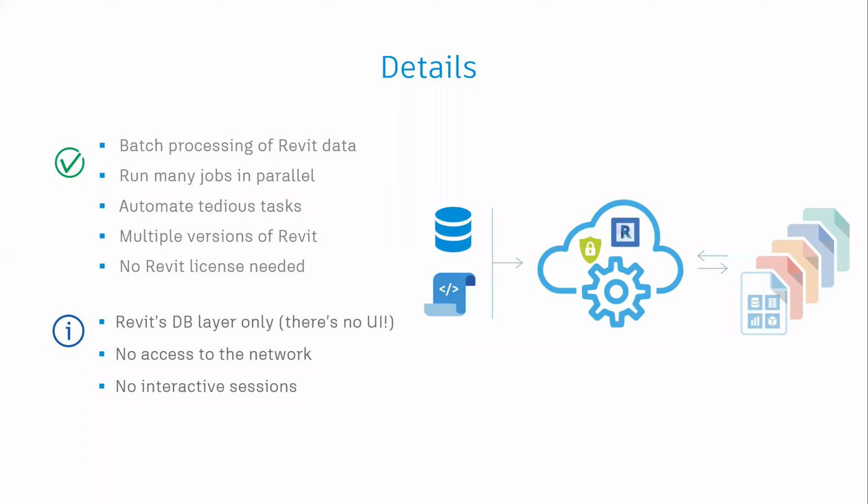And that part, the user input part, is the thing that gets us to no interactive sessions. This is not something where you have a Revit running in the background where you can build your own new UI. This is a batch processing engine. So it's not something where you're constantly running and communicating. What you have to do is gather all your inputs up front, process the job, and then deal with the outputs. It's still possible to have a UI-based experience. It just can't be live where you're actively working with a Revit session.